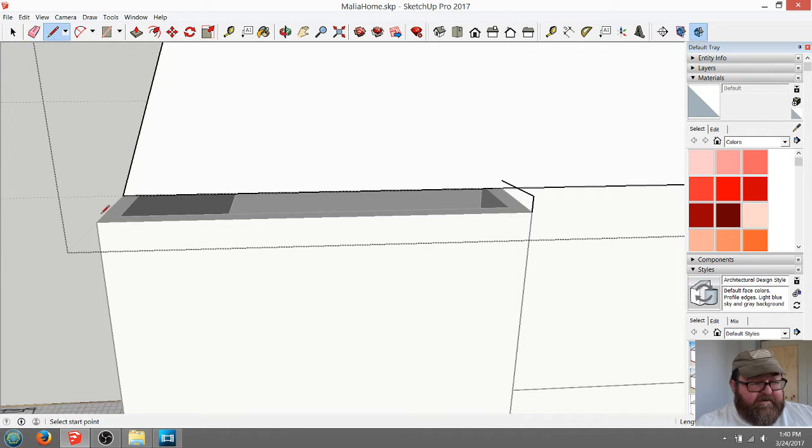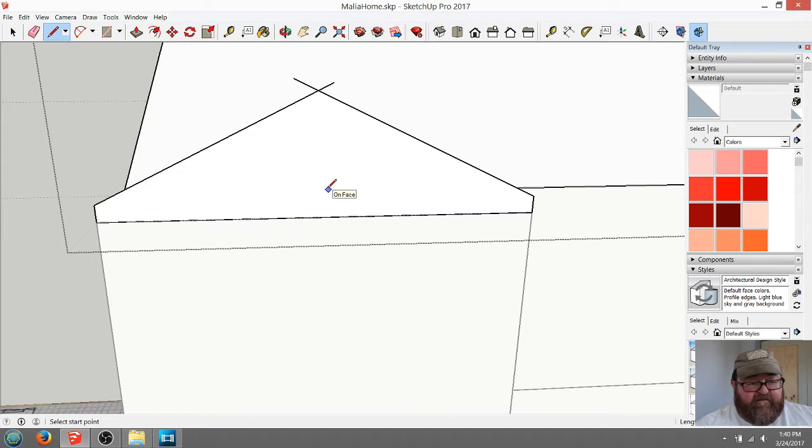Now this is kind of crude, but you get in the habit of doing something one way. And I know the reason I'm leaving 6 inches on the height here is because I know the rafter tails are not sitting right on top of the wall. I know they don't go down to nothing. And giving yourself a little height is better. And I was wondering why that didn't. There we go.